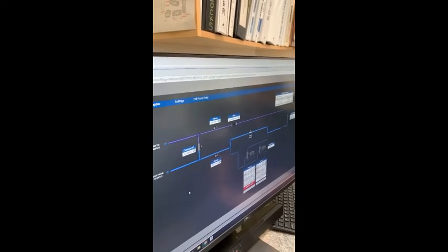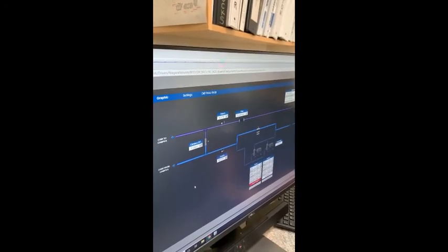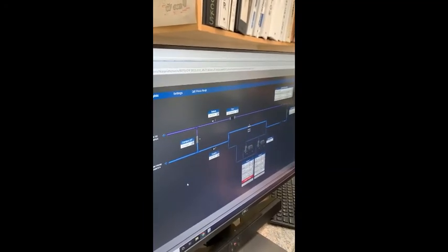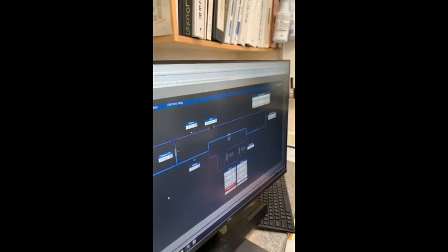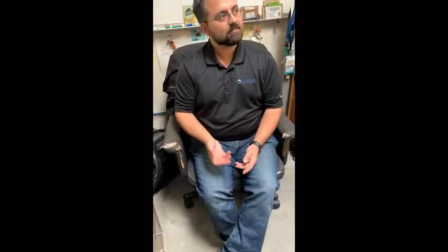We found that a lot of the alarms, I know, were caused because they went through and replaced all the condensate flow switches, or float switches, because they weren't the right size. They wouldn't trip until after it was overflowing and coming down, which kind of destroys the purpose of them.